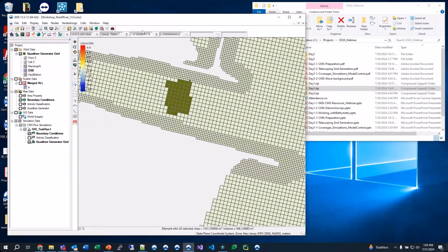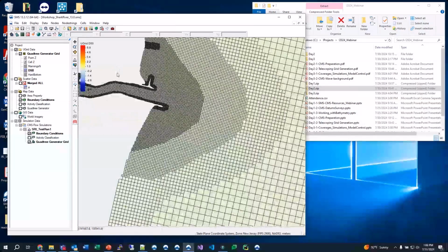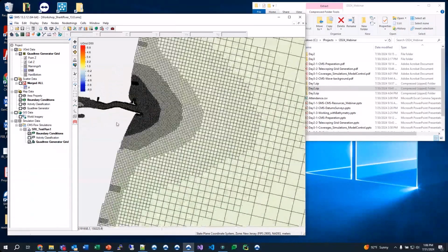And once those are selected, then you're able to change this S value. Never change the Z value unless you're wanting to change the bathymetry. But this S stands for scalar, for these scalar data sets. And so you would change this value. It would modify the value for these individual cells and then leave the rest alone. And so you'll do this on occasion. Hard bottom, you would apply this to your jetties, your bridge pilings, areas where there's large turbulence. The Manning's n would be affected in different places. So you would just set this up and use that way of changing those values as needed for your particular project.